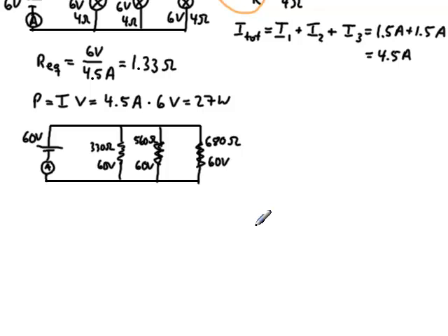Ohm's law applies separately to each branch. So each one of them is going to get some current. By the way, which one gets the most current? And you may have heard this before, the path of least resistance, and that indeed is this one here, the one with the 330 will end up with the largest current. And I'll show you in just a moment, because Ohm's law applies separately to each branch.